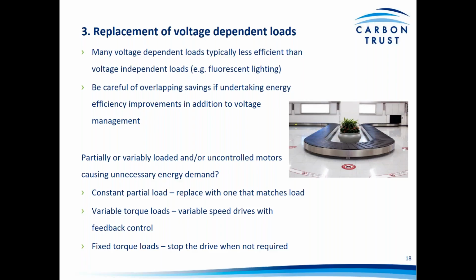Also, just to flag a couple of other things, partially or variably loaded and/or uncontrolled motors may be causing unnecessary energy demand at the site. So examples might be where you have a constant partial load. So maybe your motor has been oversized for the load that you actually have at site.